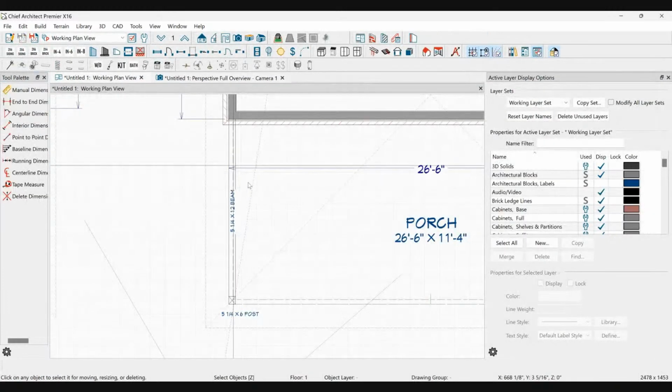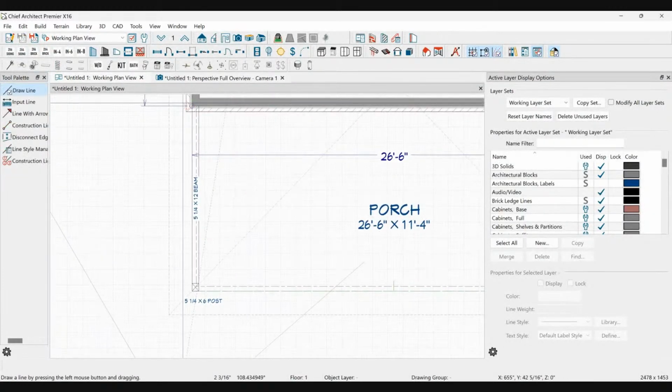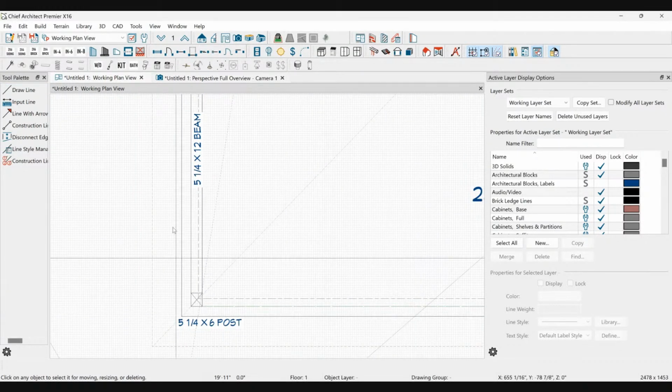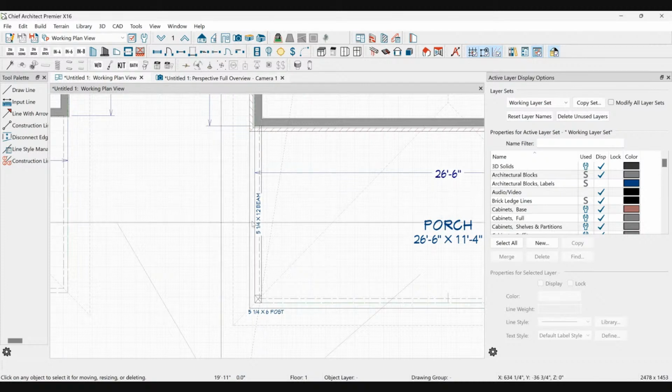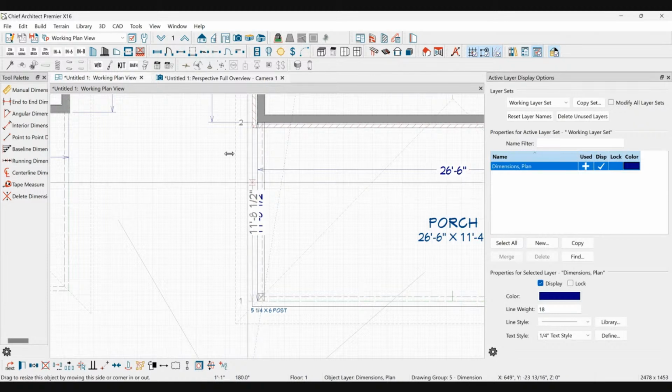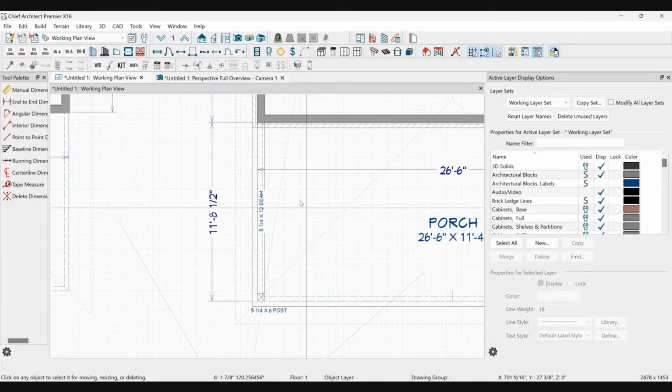And so when I draw this in my software and my plans, I would just take a line and run it out and put a solid line showing the edge of the slab. Now, when I'm dimensioning my plan, I'm not going to dimension to that line. I'm going to dimension to my framing, because the floor plan is mostly for the framers. The framers need to know that my roof geometry and all my framing is based on my wood. It's not based on my slab.